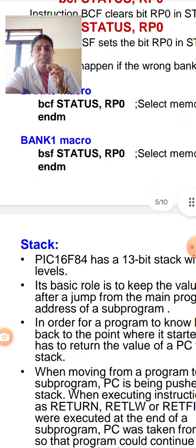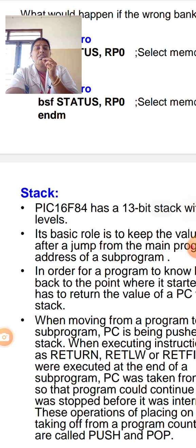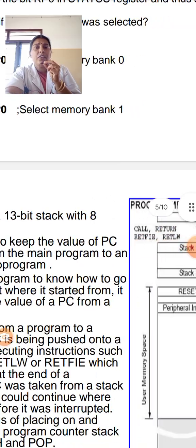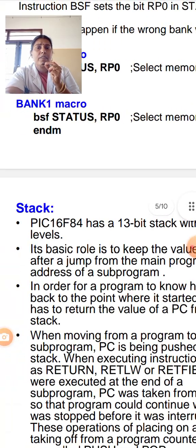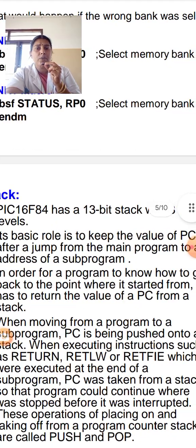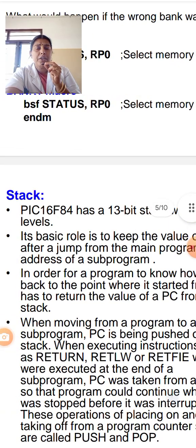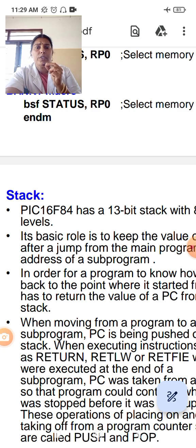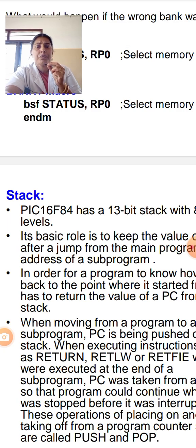Next is the stack register. In case of the PIC 16F84 microcontroller, it has a 13-bit stack register with 8 stack levels. Its basic role is to keep the value of the program counter after a jump from the main program to an address of a subprogram. In order for the program to know